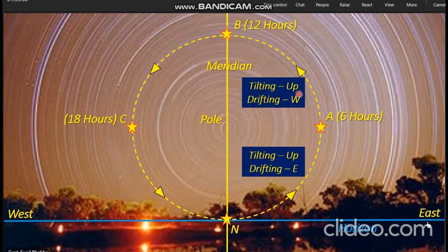And the second thing which you notice, when the gyrostar is moving from point alpha to point Bravo, it is moving in the westerly direction now. See, the left side in the diagram is the westerly direction, and the star's azimuth is now moving in the westerly direction. So the spin axis will also be drifting westerly.